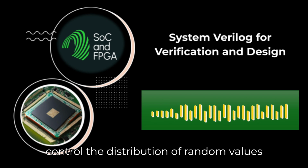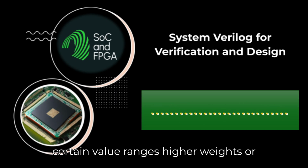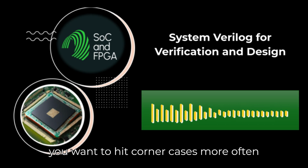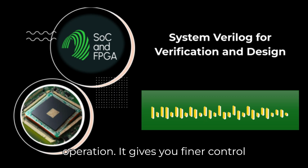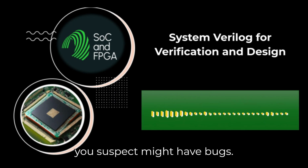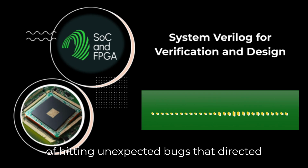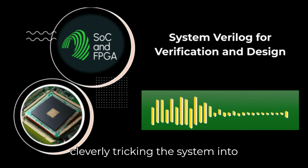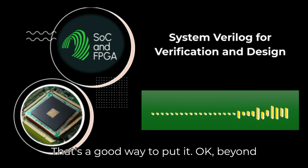You can also control the distribution of random values using the dist operator. You can give certain value ranges higher weights or ensure equal probability. Why would you want to control the distribution? Maybe you want to hit corner cases more often or focus testing on specific modes of operation. It gives you finer control over the random stimulus to target areas you suspect might have bugs. CRV fundamentally increases the chances of hitting unexpected bugs that directed tests would likely miss. It's like cleverly tricking the system into revealing its hidden flaws by exploring scenarios humans might not even think of. That's a good way to put it.